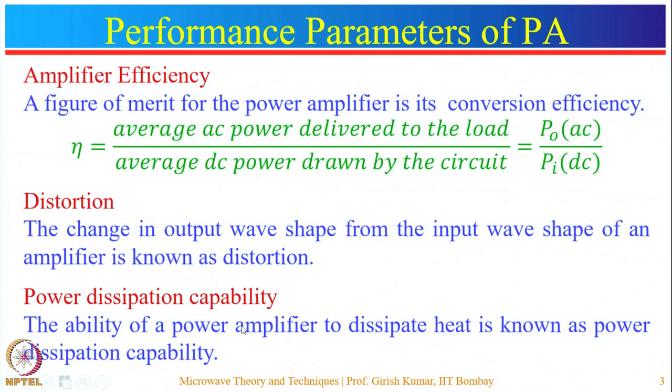If the power is not very high, then cooling is provided through the metal casing of the transistor, which dissipates heat. The transistor can also be cooled by placing it at the back end of the circuitry, and in this case the heat goes away through convection when air flows, which makes the transistor relatively cool. So, these are the main considerations of a power amplifier.